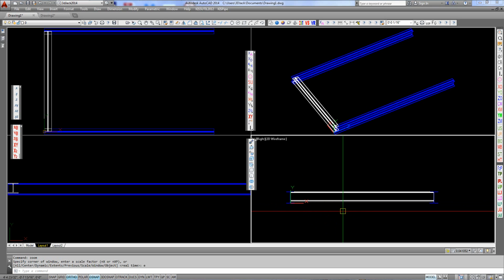And that's all I'm going to do for this. Hopefully this will help you to be able to do all the rest of them, because it's all the same thing. You put your steel in, you orient it the way you want it to be, and then you put it up against the web or the face that you need to extrude it from, and then extrude it to the matching part on the other beam or whatever it is. And that's all I can do, and good luck.